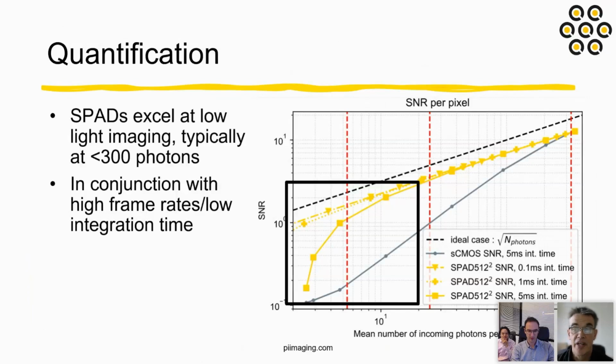So question about LiDAR. What are the potential challenges in cost reduction for mass market applications such as LiDAR? So just that's something you see in the future. So LiDAR has been one of the fields that SPADs attacked really early on. Mass adoption or cost reduction requires to focus on a single application, fixate not only the image sensor or detector, but also the system, and then mass produce it in high volume. Of course, high volume reduces the price. So in principle, the cost structure for high volume for SPADs is very similar to scientific CMOS or CMOS in general.